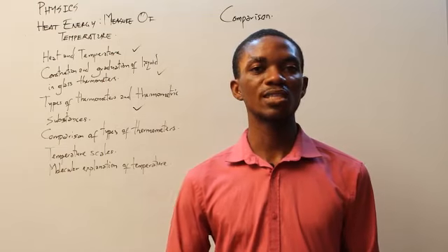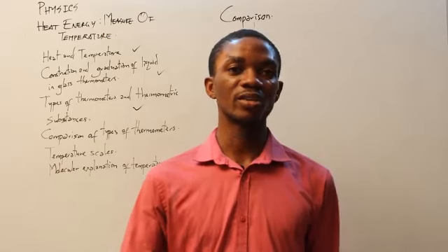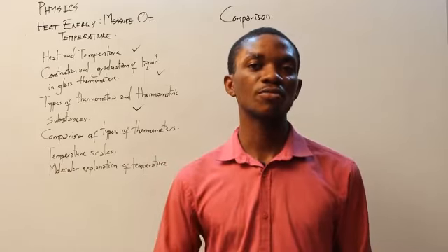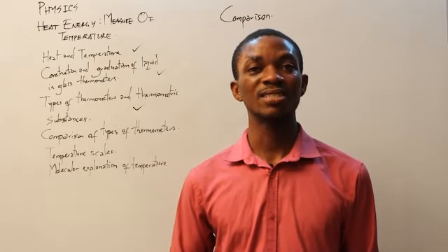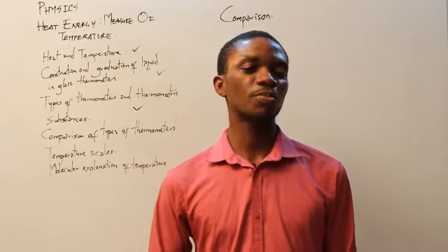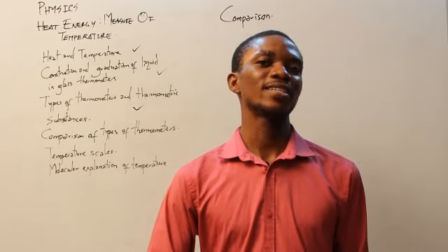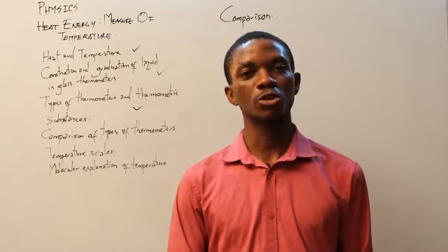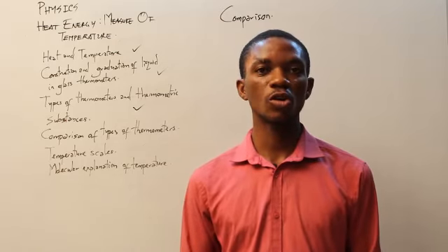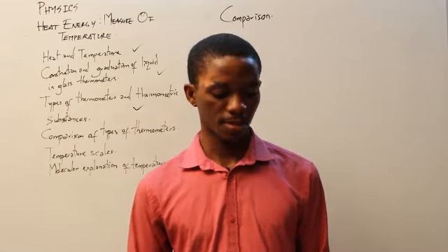The complexity of setting it up and reading it, that is until you have actually done the graduation of the constant volume gas thermometers, is very tedious and very complex. Also, knowledge of pressure is very, very important. If there is any alteration in atmospheric pressure, it would actually affect the measurements taken from this particular system.